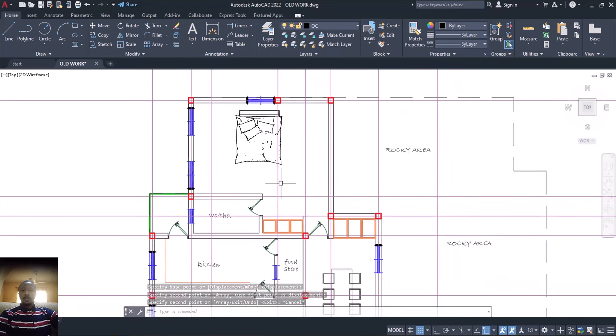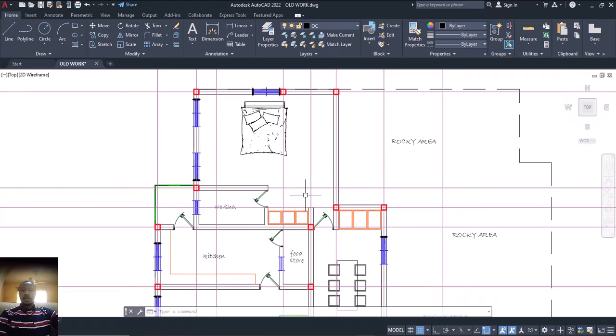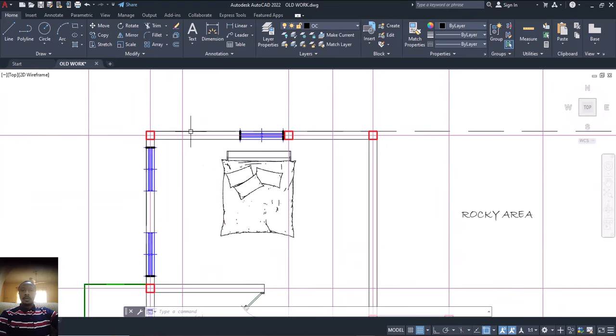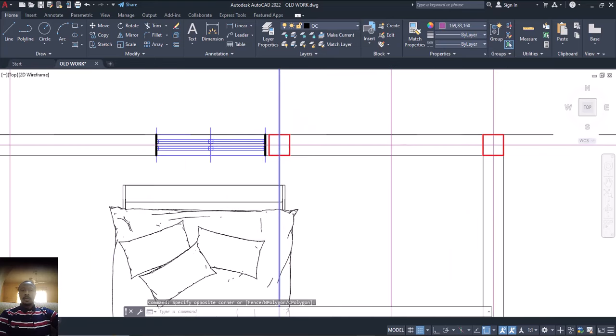Automatically, the same thing might need to happen here. If the same thing is going to happen here, this is where I talk about your judgment. Looking at this place now, I cannot come here and put a column, because of what we have here. I need to put another one here, isn't it? And if I put another line to have another column here, I'll be having too many axes. So on that ground, since from here to here is the same as from here to here, what's stopping me from shifting this one like this? Then CP, enter.